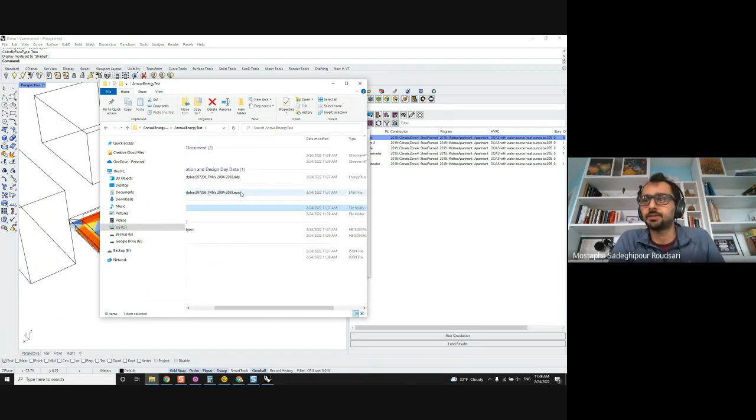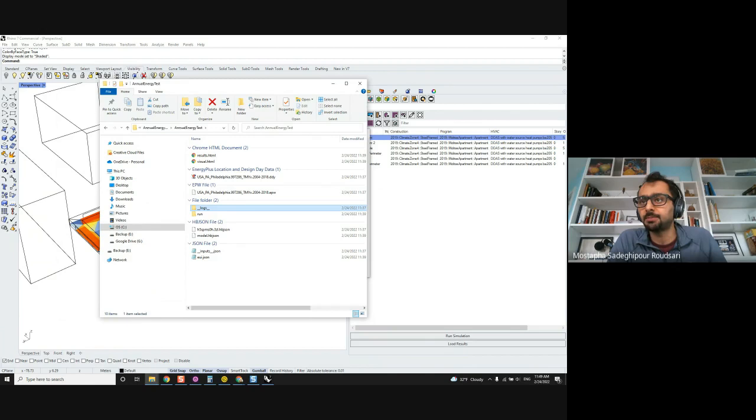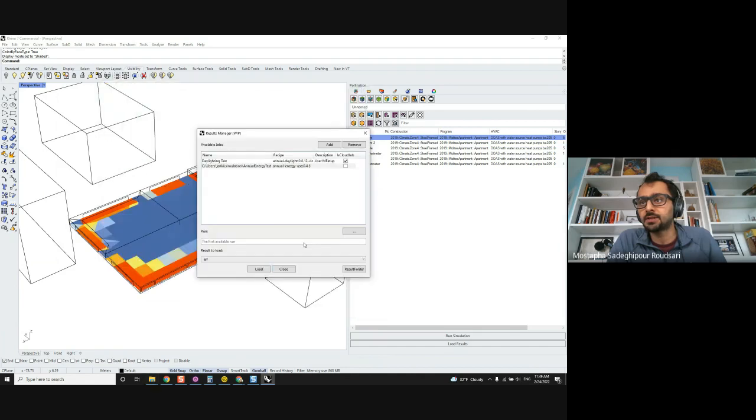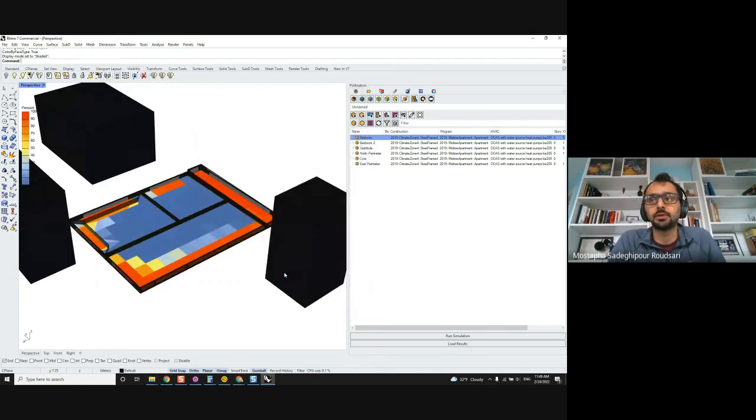So we have another question. Brett is asking, do you have any geometry commands that help create closed solids from surfaces that are near each other? If an architectural model has interior walls that aren't quite attached to exterior walls in a direct import. We don't, but Rhino has a lot of commands that can help you do that. If you share a sample on Discourse, we can help you there.